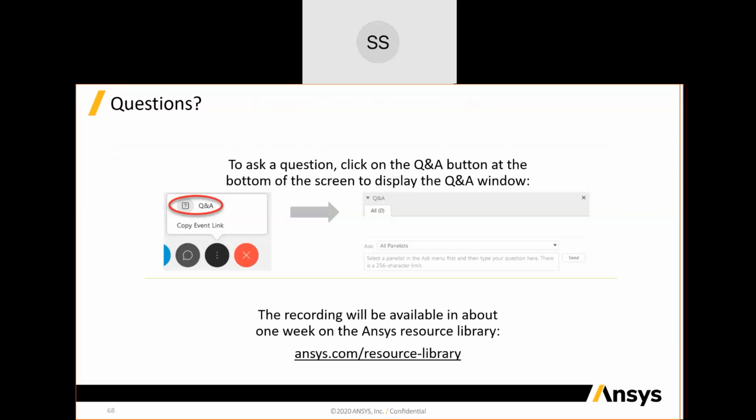Peter, we have one right here. Can I expand this optimization to a channel optimization where the channel is extracted with 3D layout and then linked to a transient circuit simulation for an eye analysis? Yeah, so that's of course easily done if you're just sticking inside the tools in electronics desktop. So you can have the Ansys circuit solver consume the 3D layout simulation to just very easily set up an eye analysis or to produce an eye diagram.